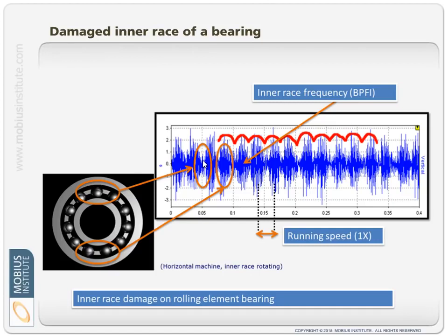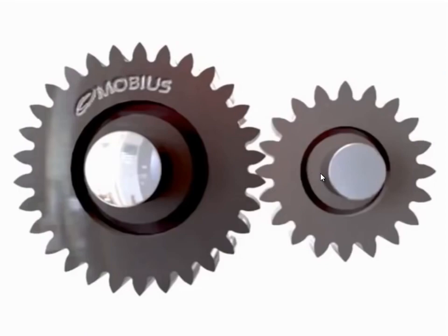This time waveform tells me about the nature of the fault condition and the severity. How many G's of vibration tells me how severe the problem is, and it's something that I can monitor over time. So that's a very useful sort of display.